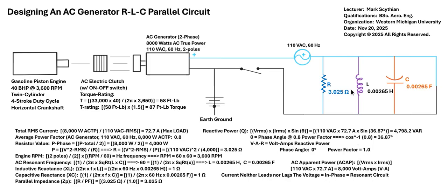So the one obstacle to circuit designers is the best answers come from the best questions. So a good question to ask is, can you design an AC RLC electrical circuit with a power factor of 1.0 to be matched to a generator with 0.8? And yeah, the answer is yes, you can. It's actually encouraged, but it's often not talked about.